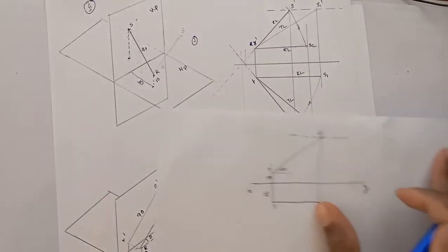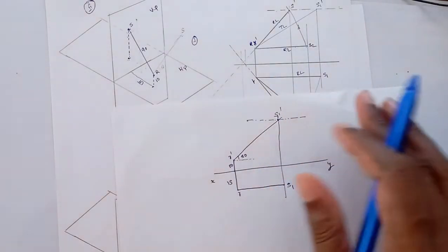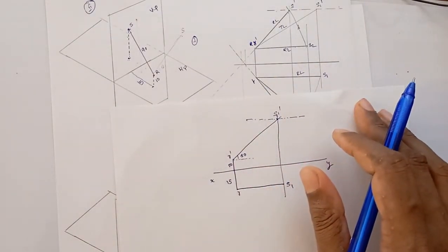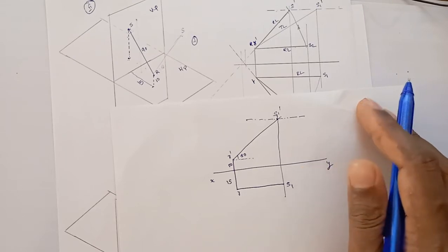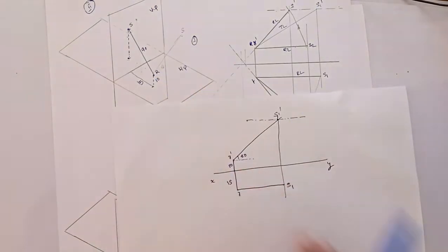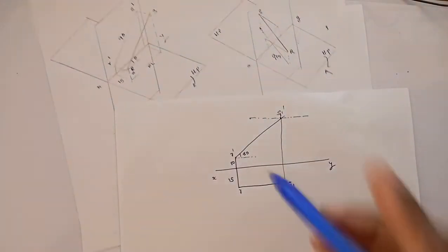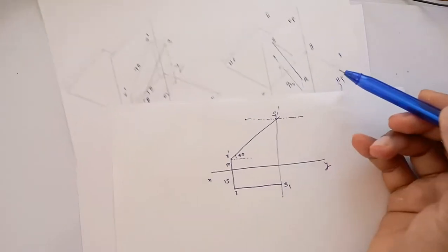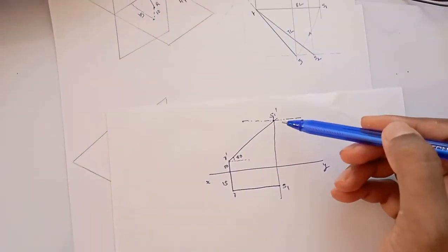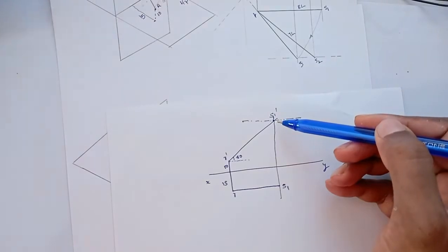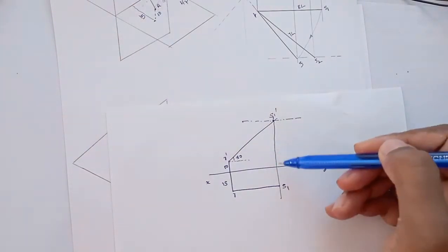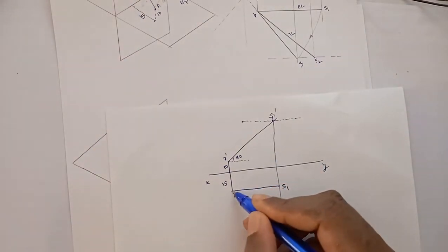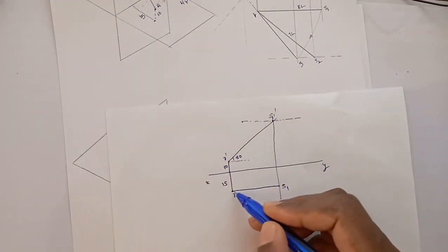The next step is make the line parallel to HP, keeping the angle with VP constant. That means keeping the phi constant. So it will be like this. So here this is the position. So after horizontal plane, and this is the point S in second quadrant. So whatever the views, front view and top view, all the views will be above XY line. So this is the top view of the point R.